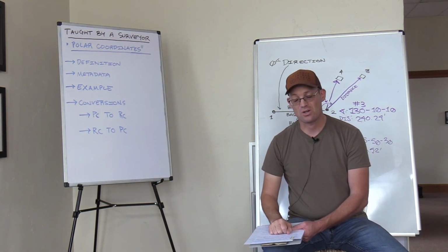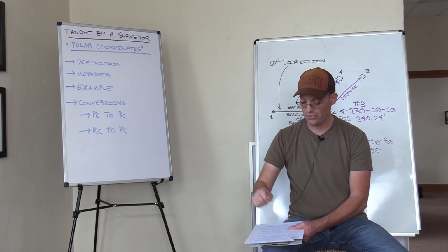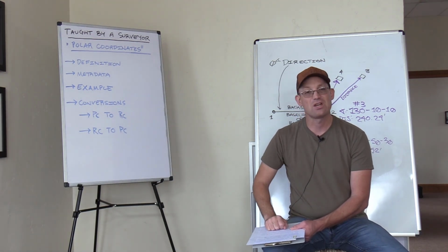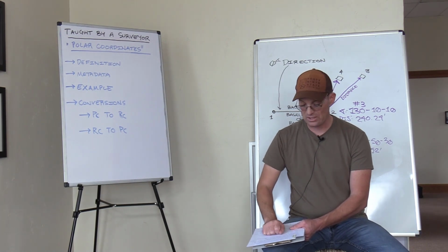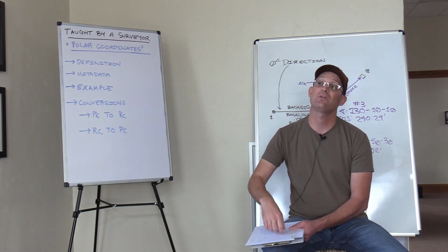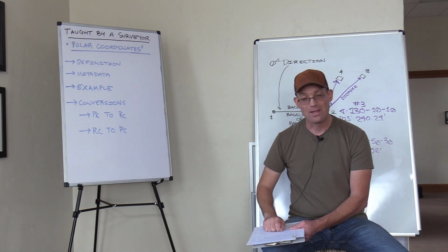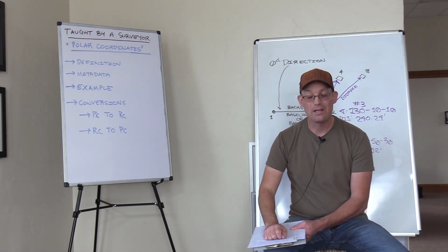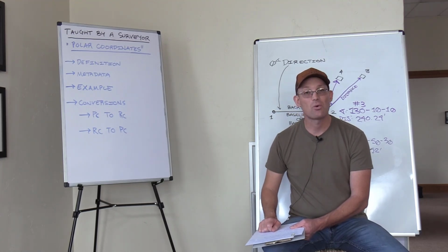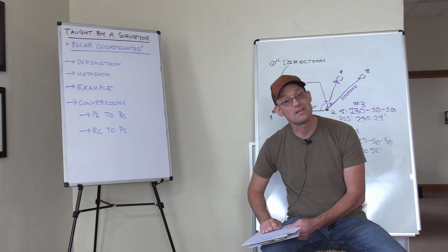They didn't have calculators or computers. They would use a book of trig tables, and they would calculate all the change in northings, change in eastings, and they'd calculate their 2D coordinates, right? And then when they were going to go back out in the field to do layout or stakeout, they would go do that math. They'd calculate, all right, if I'm at this point and I need to stake out these 3 coordinates, what's the angles and distances that I need to turn?